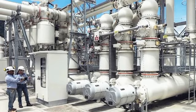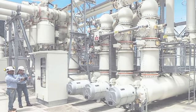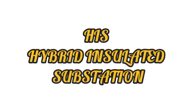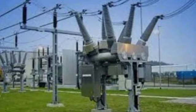Equipment is housed in metal-enclosed SF6 gas compartments, compact, low maintenance, suitable for urban or harsh environments, higher upfront cost but lower long-term operating expenses. HIS, Hybrid Insulated Substation. Combines features of AIS and GIS, optimizes space and cost, often used in retrofitting or partial upgrades.